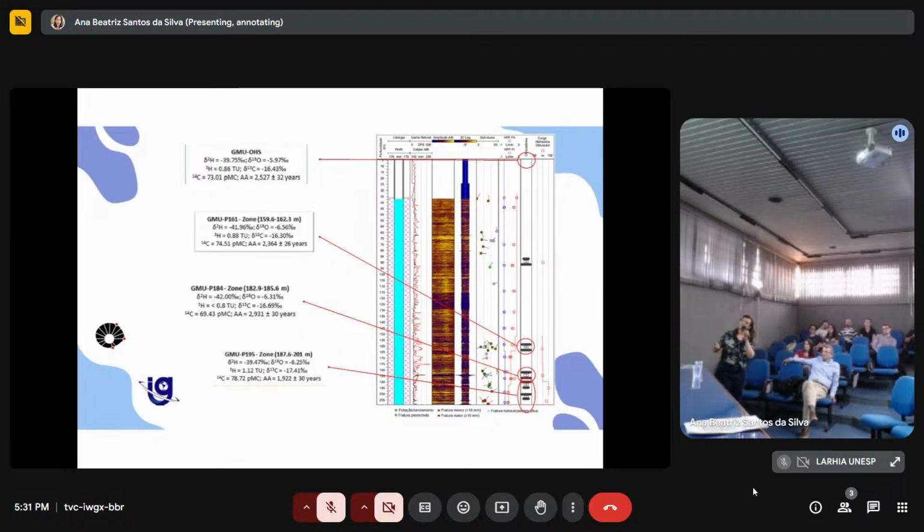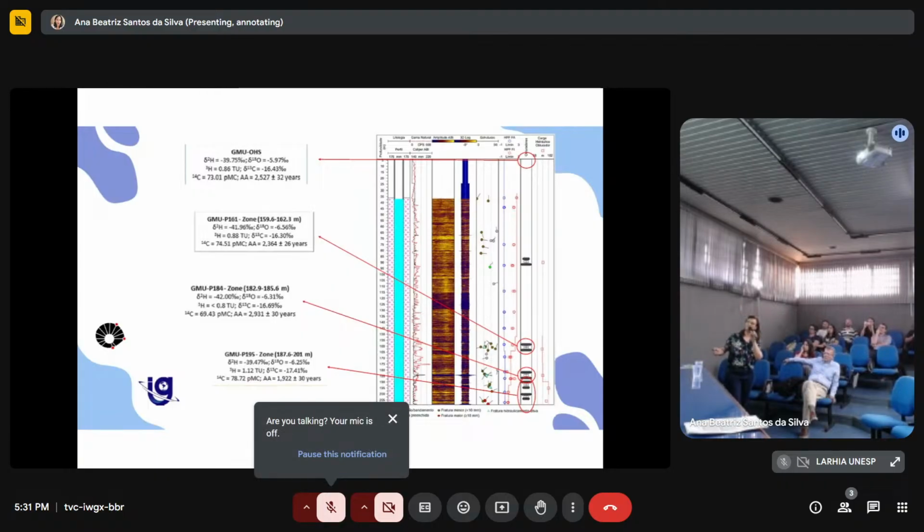Here we have the information from the geophysics logging, the acoustic borehole logging also, and from this information we interpreted the fractures, the structures that were crossed by the well. So here, this row is the interpretation of the structures. Here you have the results of the heat pulse flow meter, which shows that the flux is upward. And here we have the positions where we placed the packers.